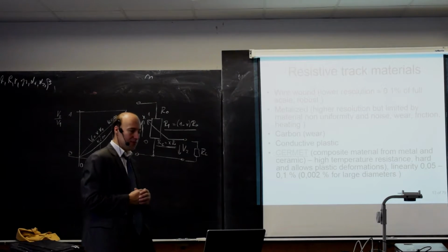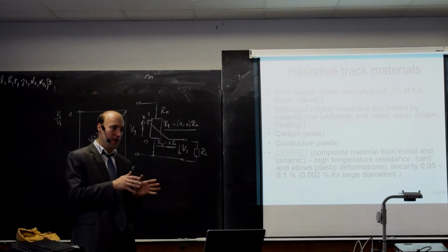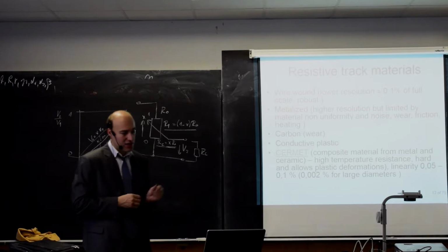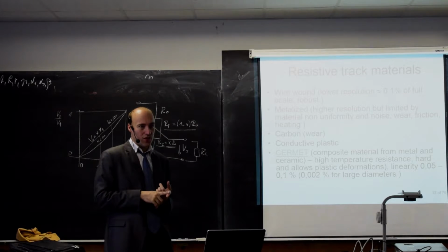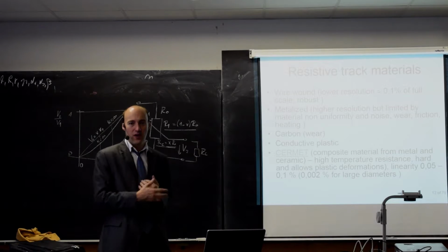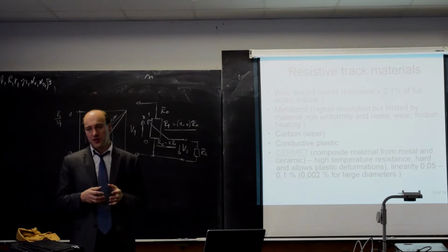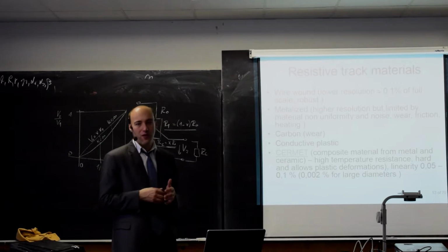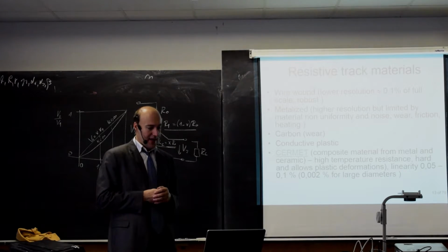And you have a problem with low resolution. Imagine we have a wire, this wire has some diameter, and we are basically switching between those wires. So a wire wound resistor used as a sensor has a lower resolution compared to the other principles. But on the other hand, it's robust. It's good for environments where you have vibrations, where you have humidity and so on.